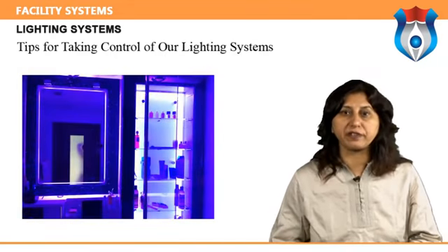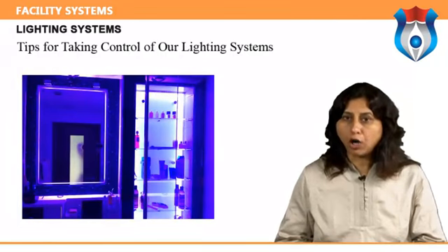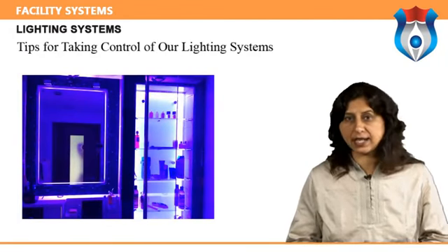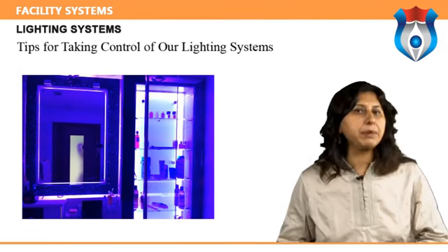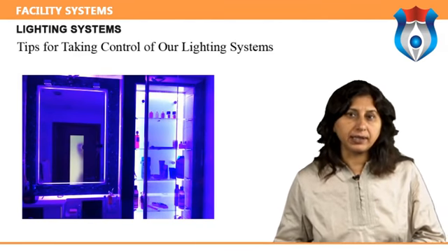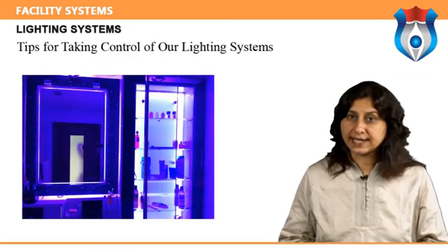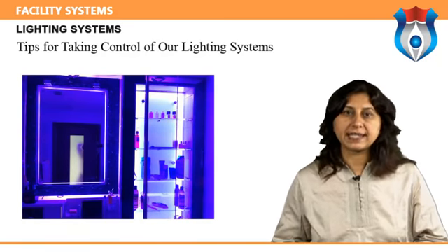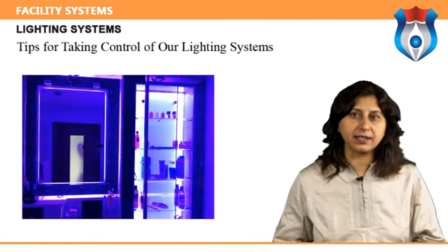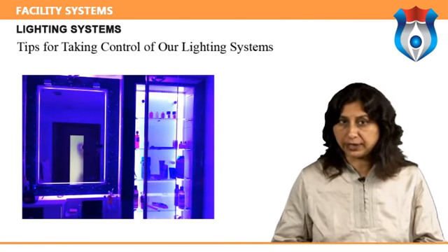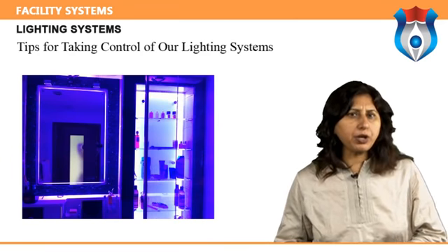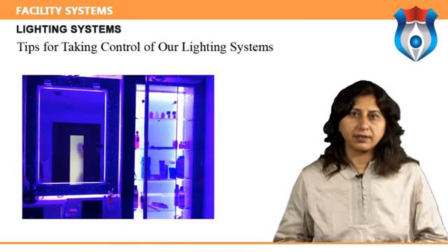The challenge of effectively specifying occupancy sensors involves selecting the right sensor technology. Examples include ultrasonic, passive infrared, sound, or combination dual technology. Standard occupancy sensors also require manual adjustment of their sensitivity and time delay to avoid false triggering.